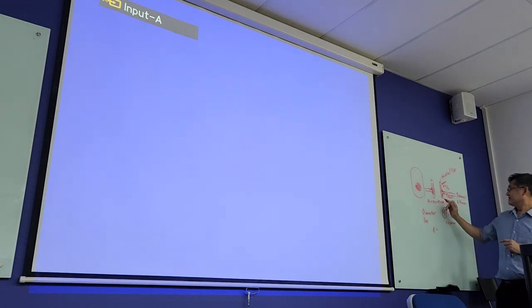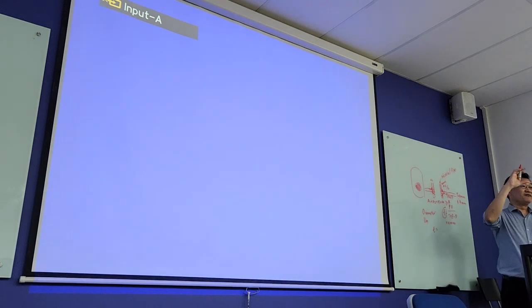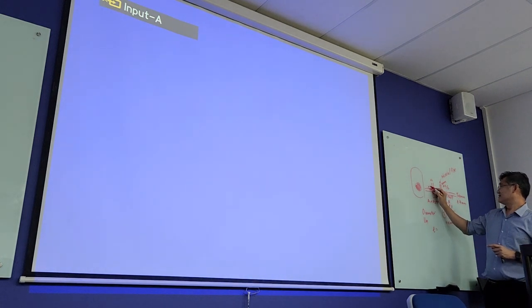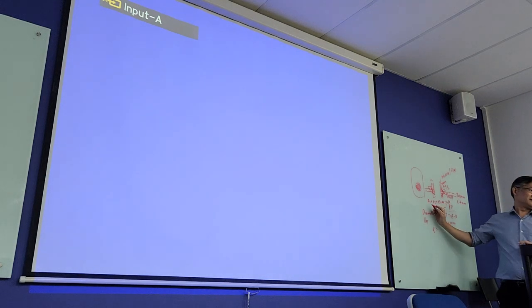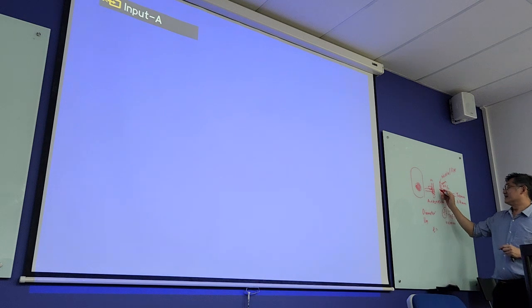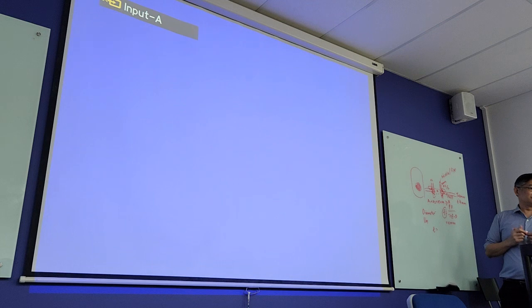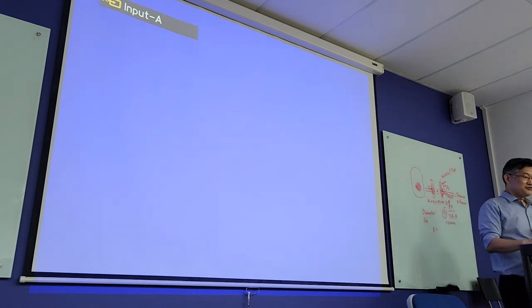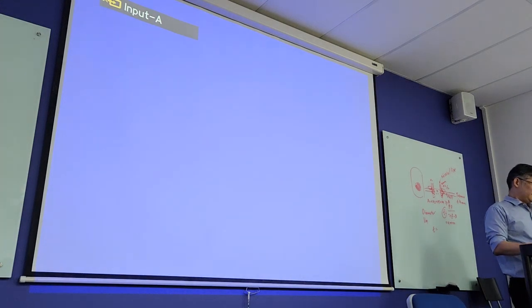But if A1 plus A2 plus A3 plus A4 is smaller than your A, you have to use a reinforcing ring. We call this reinforcing ring A5. This reinforcing ring will enhance, such that you are able to increase the area to compensate the lost area of A. Okay, so with this idea, we know we can do your question 5.